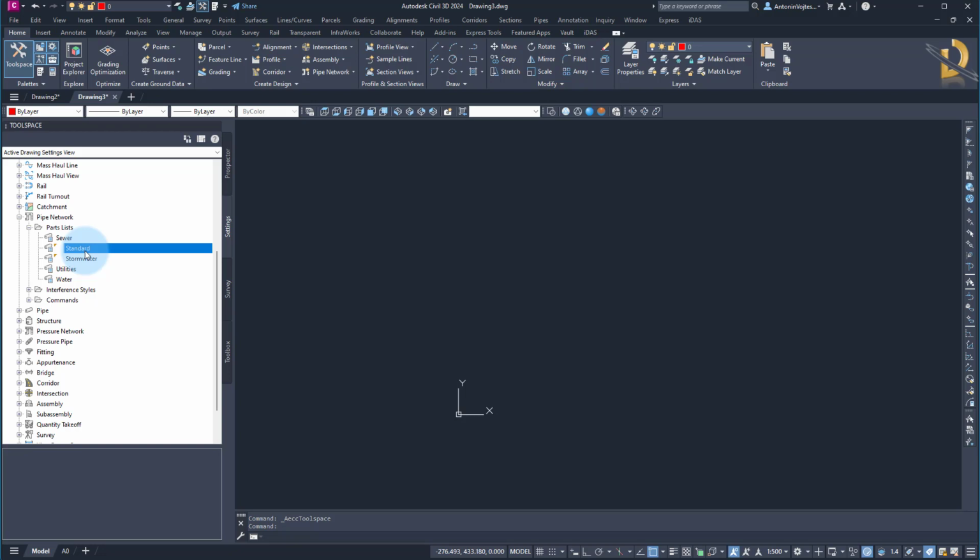So let me highlight again, if you want to start a project in Civil 3D, you must start with a correct template. Otherwise, you will struggle with the styles and with the parts that will be available to you in a part list.